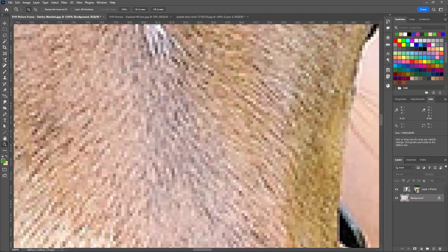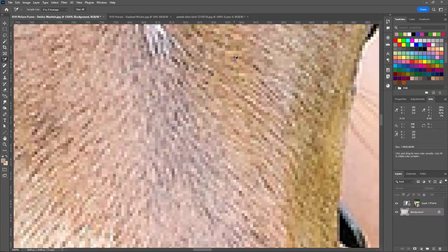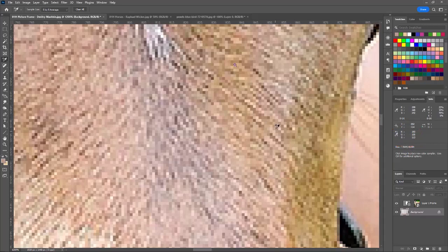So again, if we go back to the eyedropper tool, we're clicking on an individual pixel and setting the foreground color to that color. But with the color sampler tool on the options bar, we can still do a point sample, but we can also do a 3x3 average or a 5x5 average. So I'm going to do the 5x5 average, and we'll come in and click on a pixel here. So it's looking at the 5x5 pixels around that, and it's putting in the information the average of those as far as the red, green, blue. And I could then click on another color.